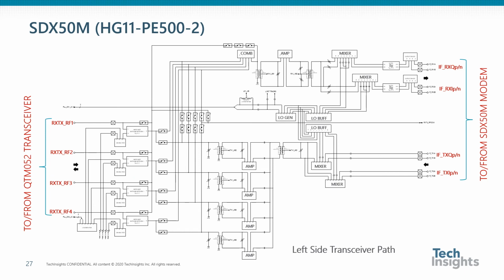This is the architecture schematic of the left side transceiver. First of all, consider the receive path. The 4 unbalanced IF signals enter this chip on the left and pass through an impedance matching circuit, then pass through an RX-TX switch network. The 4 RX path branches off to the top, at which point they are combined in what looks like a resistive combiner. The data signal then passes through a balun to generate a differential signal.